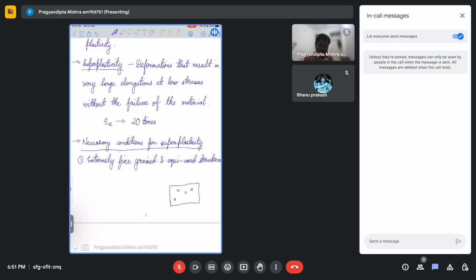Now these grains will start growing slowly. This grain will become bigger and bigger, and similarly other grains will also become bigger, till they hit the next grain, after which all the liquid becomes solid. So all these grains are growing simultaneously, and they will hit each other at some point and become individual grains.